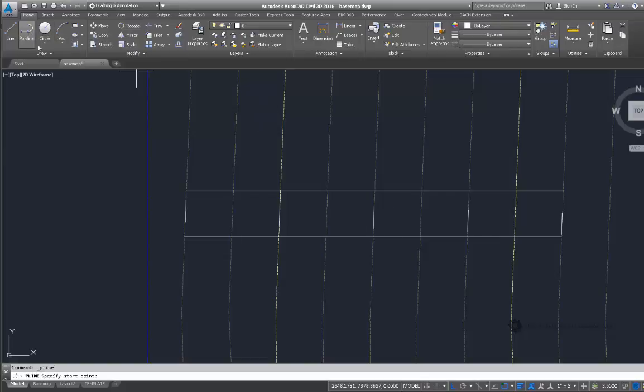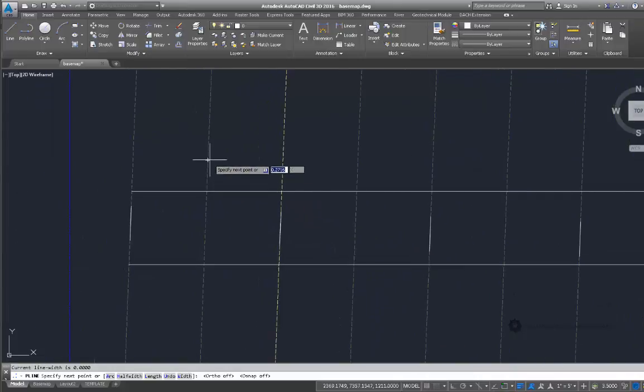So now I'm going to use my polyline tool and start sketching in my contour. I want to tie in here, and then once I click here, I need to turn off my ortho and my snap. And I'm always going to kind of snap to this contour, and when I do that, I know that my proposed line work is going to pick up that elevation because I snapped to this elevation. We'll see that here in a minute.